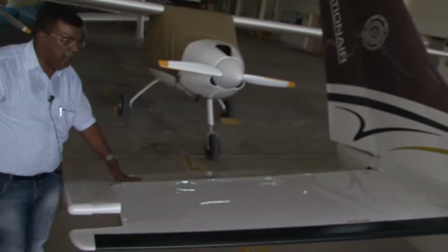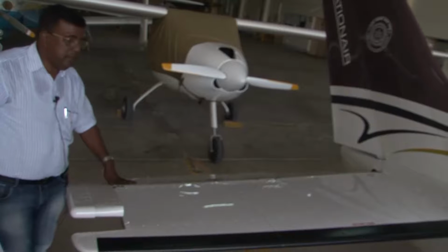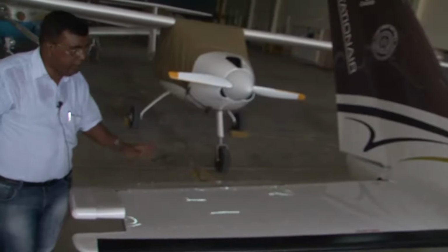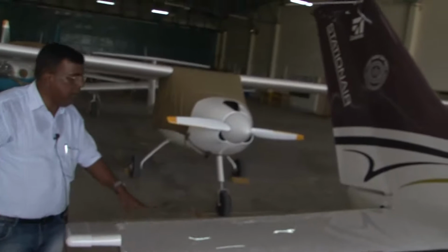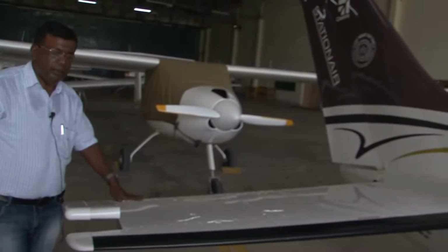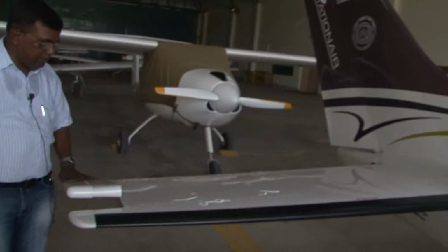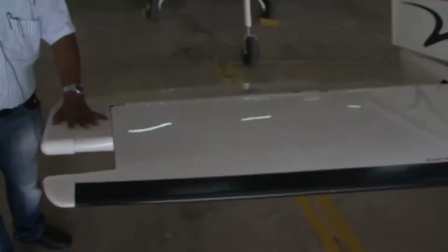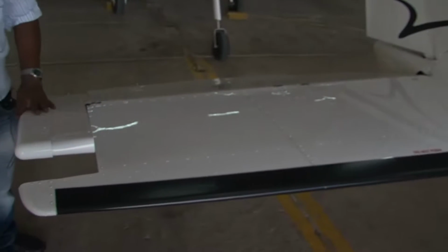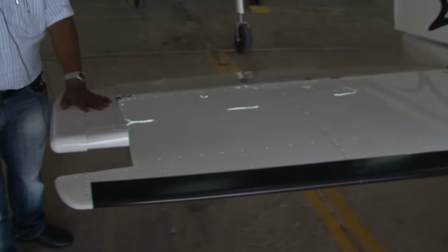So when I am conceptualizing a design, I will keep around 30%, although through analysis we will also find out the number, and whatever number I get through analysis, I cross-check whether I am really making sense or not, whether these numbers are conforming to the conventional tail or not. Right? You'll also find there's some portion of the tail elevator somewhere here, and why this is given. Many airplanes may not have this, so we'll talk about this portion also, how it's going to help in the handling qualities of the airplane.